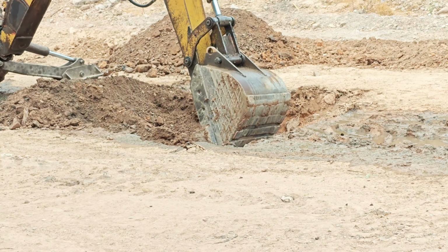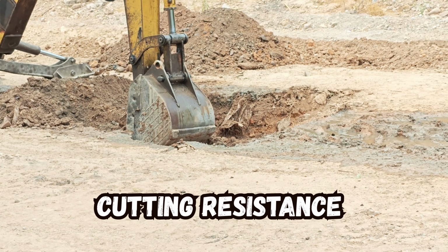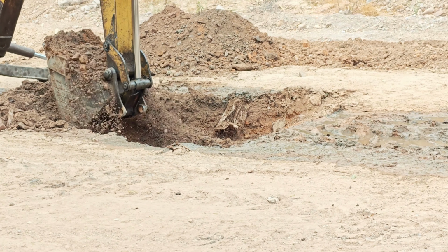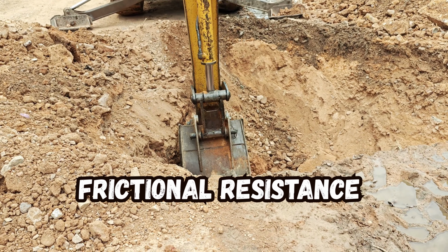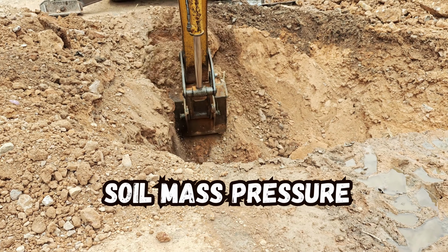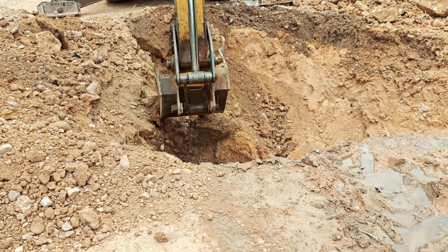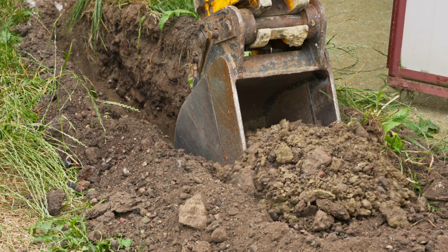Once the bucket contacts the ground, it must overcome several types of soil resistance forces. The most significant of these is cutting resistance, which is the force required to break and separate soil particles as the bucket penetrates the ground. In addition to this, the bucket also experiences frictional resistance as soil slides along the inner surfaces of the bucket. Another important component is the passive earth pressure exerted by the surrounding soil mass, which pushes back against the bucket during penetration. The magnitude of these resistance forces depends greatly on the type and condition of the soil.